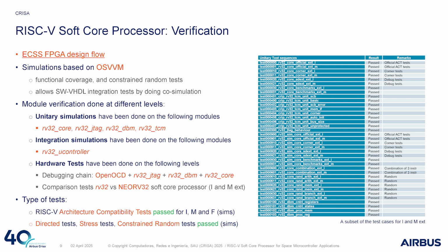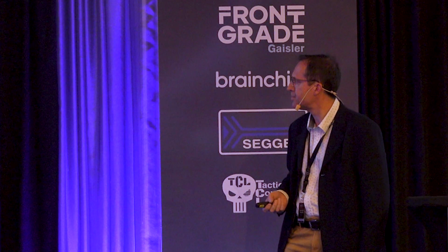We have done the verification at different levels. From the unitary point of view, we have run the verifications of the core, JTAG, debug module, TCMs, and the integration level in the microcontroller. We also have tested in hardware the full debugging chain from OpenOCD down to the hardware.